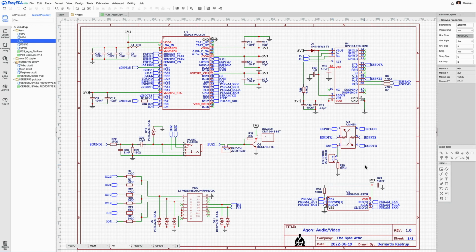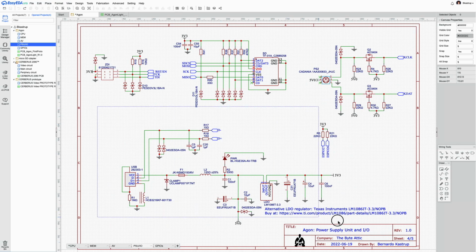So that's basically it. These key signals here are basically serial control signals. They are the same signals repeated twice, and they come from here, from the USB to serial bridge, which is U4. And depending on whether these signals are high or low, you need to reset the ESP32 or put the ESP32 in programming mode. This does the programming mode, and this is the reset for the ESP32. It also happens to be a global system reset. So after the ESP32 is programmed and it's meant to be reset, the entire system will be reset, not only the ESP32.